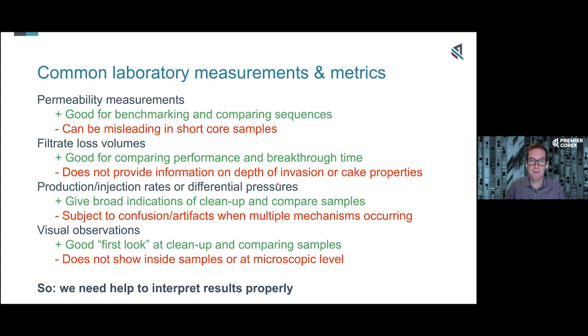And then at the same time, drilling fluid or completion fluid may go inside the reservoir and not shift out in that particular reservoir, be retained within the sample. Overall, that could equal 0 change in permeability. But when we look inside the reservoir, there's things that could cause damage and could add up to damage in the reservoir. So context is important.